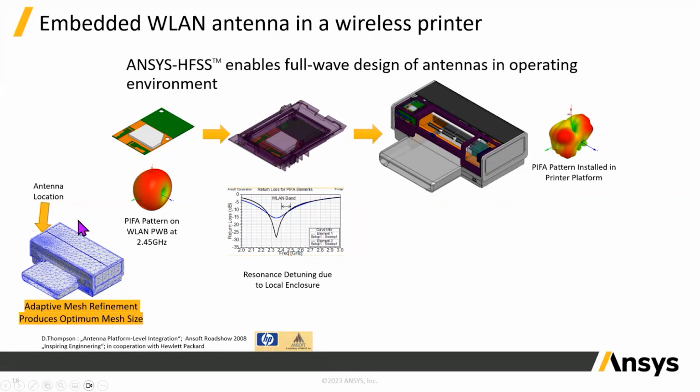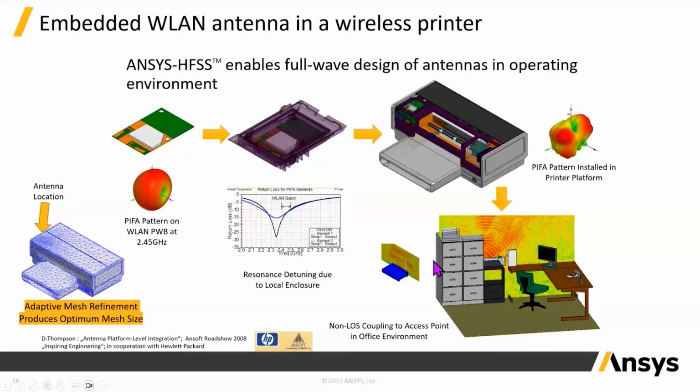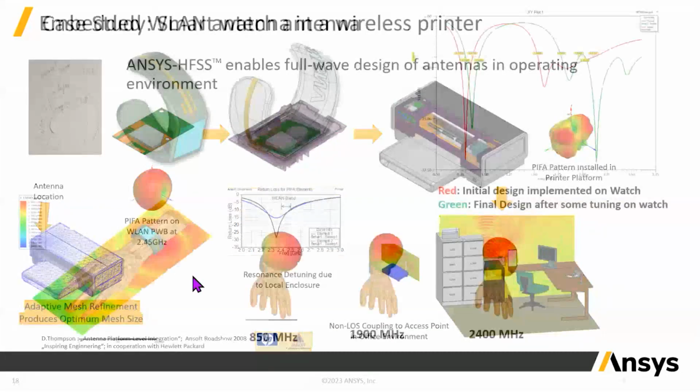It is because of the adaptive meshing process which is happening inside HFSS, which automatically finds the right locations where the electric fields are strong. In those areas the mesh will be generated more densely, and in other places where the fields are very weak, it will have a coarse mesh. So it does an automated meshing method, which reduces memory consumption and computation resource consumption, and it is always reliable in the results compared to measurement.